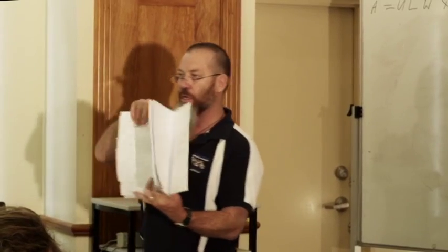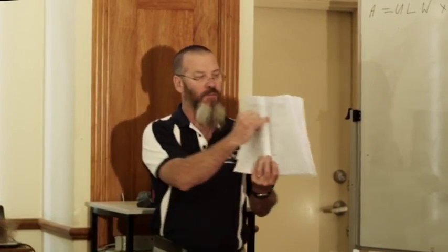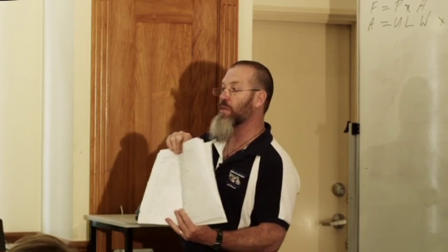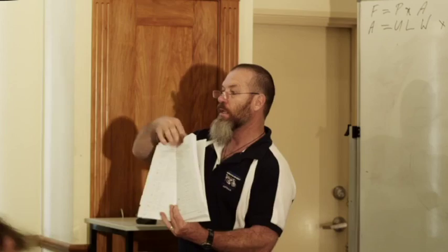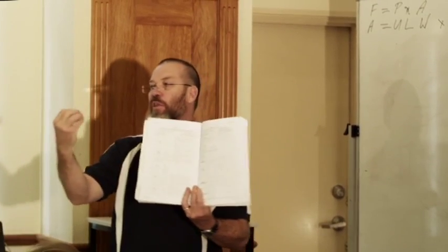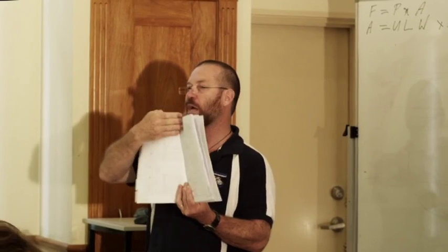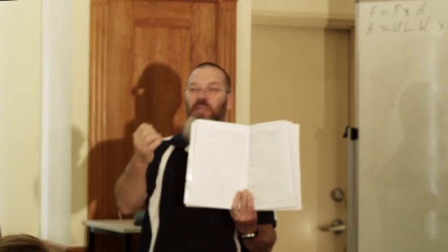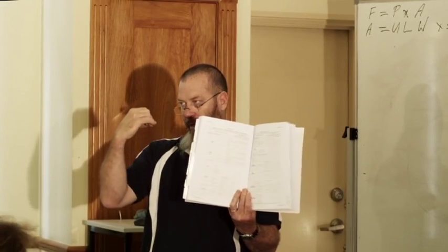Now, how these tables work, and they're all the same, first of all, you must read the heading. And the heading in this case says uplift capacity of roof batten tie-down connections. So this is where we should be looking for a batten connection. Secondly, we've selected our joint group, which is down the side here. You'll see the joint groups run down the side, and we've all agreed that we're going to use JD5. So you start at the top, you work out what the value is, you run down there, and we can't start at A, we start at B, until you find a connection that is equal to or greater than the required value.